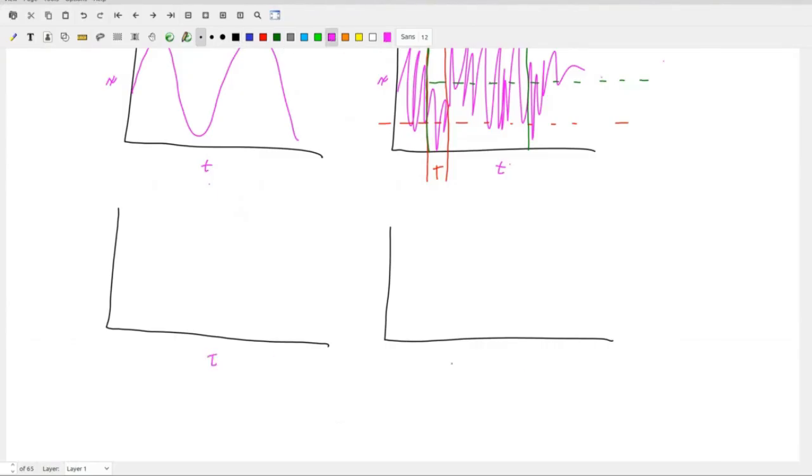So here's tau, and here's tau, and here's our RXX and our RXX, right? So our autocorrelation. If you take a sinusoid, original signal, and you have a tau of 0, you have a point and you have another point right next to it. What is your correlation between those two points? Or your point and the actual point that it is? What's the correlation between you and yourself? 1, right? So it's going to start at 1,